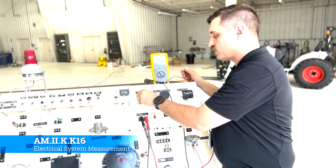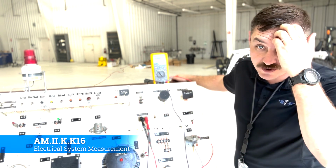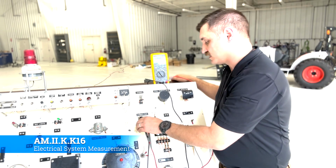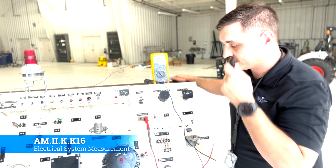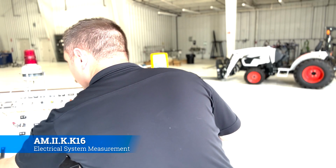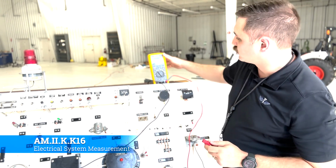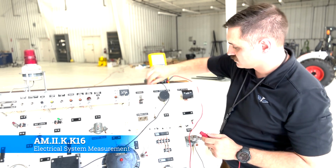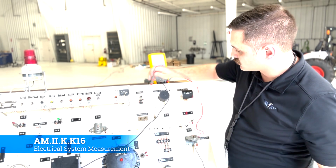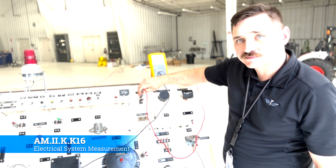At this point, we know that it's just, for whatever reason, there's no power to the socket. We can verify that there's no power to the socket simply by pinning off to ground. So we're on our ground bus now. We're on 12 volts DC. Pull the bulb out. And we're just going to pin that right there. And notice there's no power.